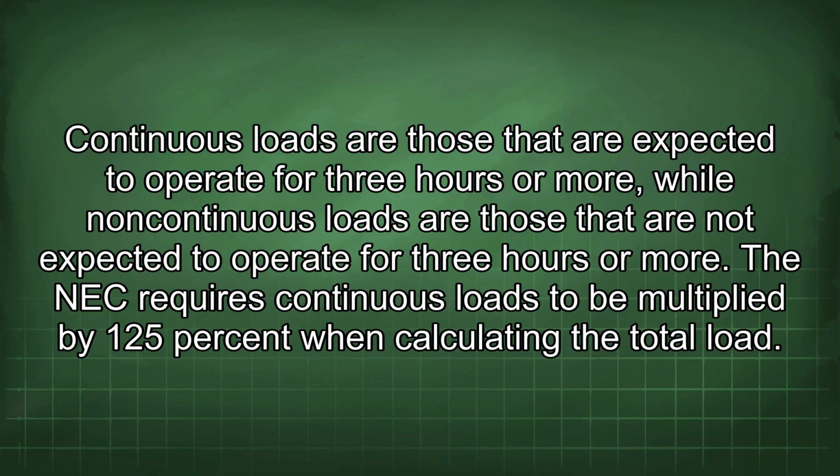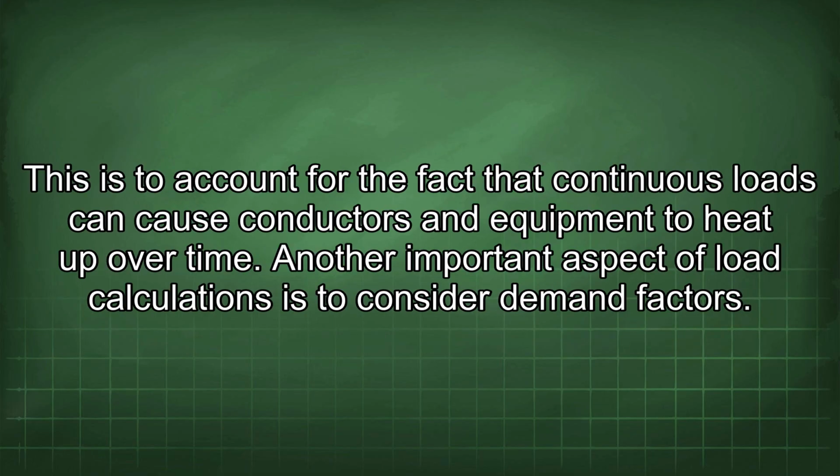The NEC requires continuous loads to be multiplied by 125% when calculating the total load. This is to account for the fact that continuous loads can cause conductors and equipment to heat up over time. Another important aspect of load calculations is to consider demand factors.